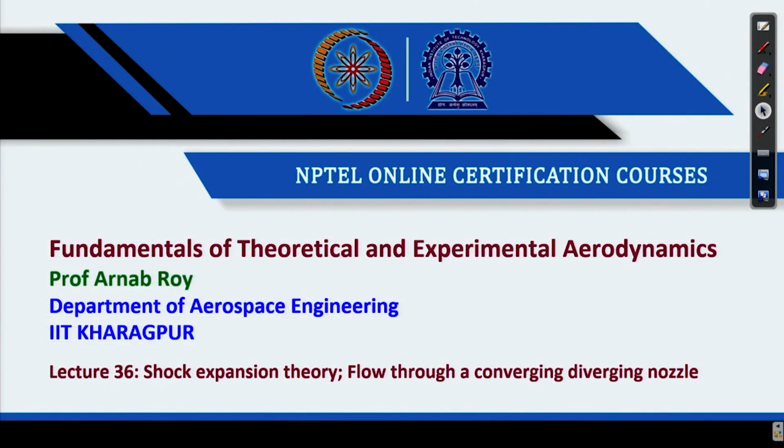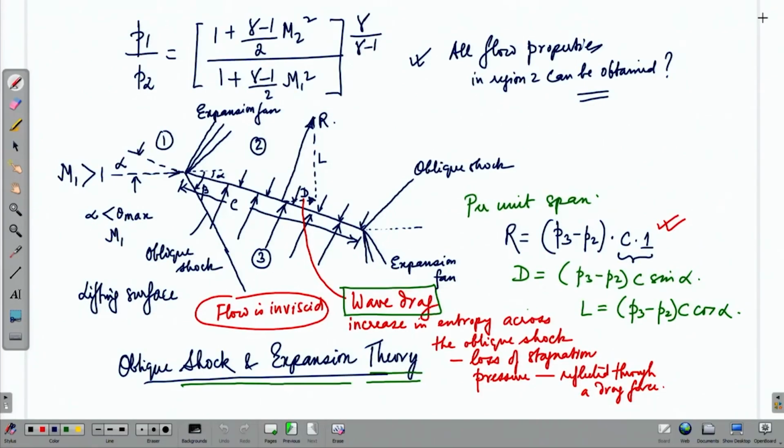In this lecture, we will discuss further on the shock expansion theory, and we will also discuss flow through a converging diverging nozzle. We recall in the last lecture, we discussed the shock expansion theory.